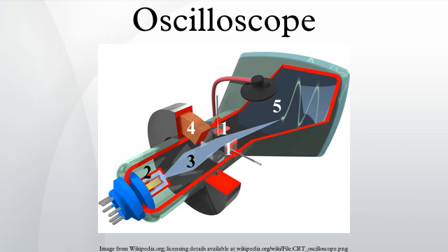Non-electrical signals can be converted to voltages and displayed. Oscilloscopes are used to observe the change of an electrical signal over time, such that voltage and time describe a shape which is continuously graphed against a calibrated scale. The observed waveform can be analyzed for such properties as amplitude, frequency, rise time, time interval, distortion and others. Modern digital instruments may calculate and display these properties directly. Originally, calculation of these values required manually measuring the waveform against the scales built into the screen of the instrument.